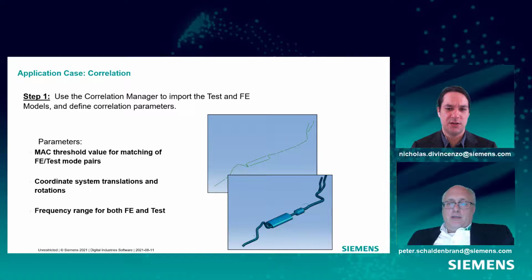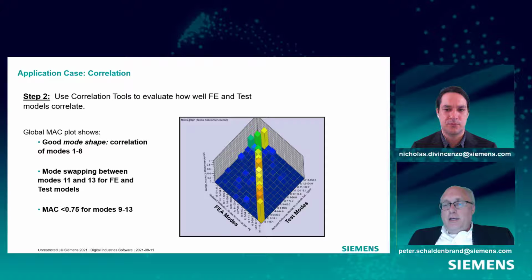Well, I guess we could look at both the natural frequencies from test to simulation. We hope maybe that they're similar. And I guess we could also look at the mode shapes at those natural frequencies and see how similar they are. Yeah, I like this modal thing because MAC, modal assurance criterion, we get to use a lot and a lot. But this time, instead of doing a MAC with a set of modes to itself, we're doing it between the FEA and the test modes.